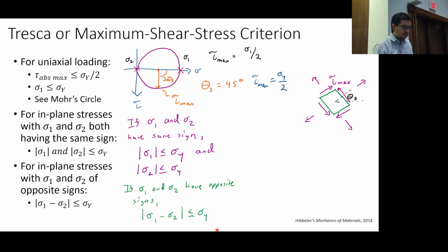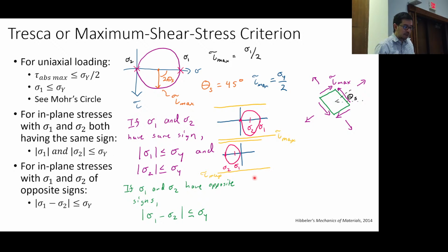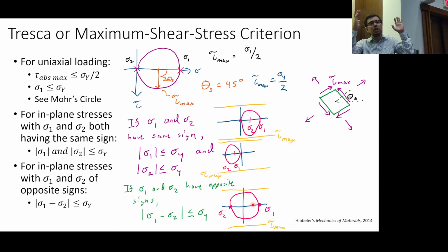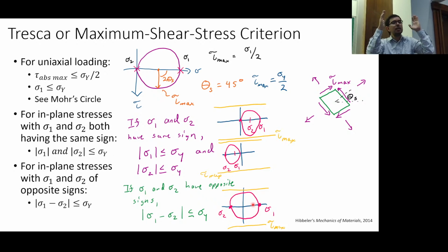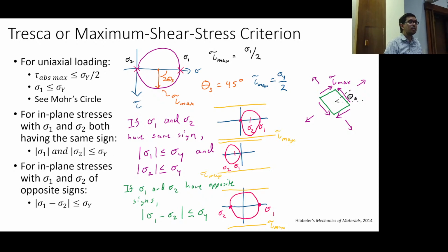So here are some of the examples where you have these tau maxes, absolute maxes, that you're interested in, making sure that your Mohr's circles are in the bounds. Okay, and here's another case. So we talked about field goals for maximum normal stress. Maximum shear stress, it's more like you're going down the highway. I don't know, because a field goal is vertical and this is more horizontal. Maybe the analogy is bad, but what you got to see is that your Mohr's circle needs to be inside this limit. Okay, that's going to be the criterion.